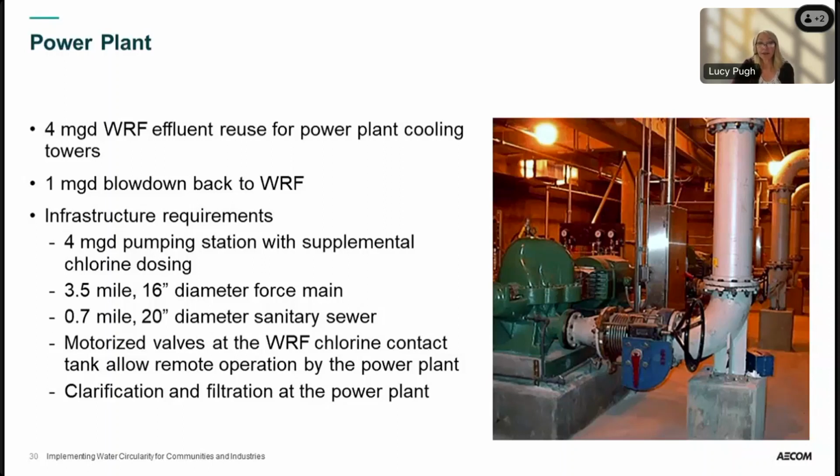So this required a pumping station at the community's water reclamation facility chlorine contact tank. The water was extracted before dechlorination. There was some supplemental chlorine dosing to maintain a chlorine residual all the way to the power plant. A 3.5 mile force main, a sanitary sewer for discharge of the blowdown water.